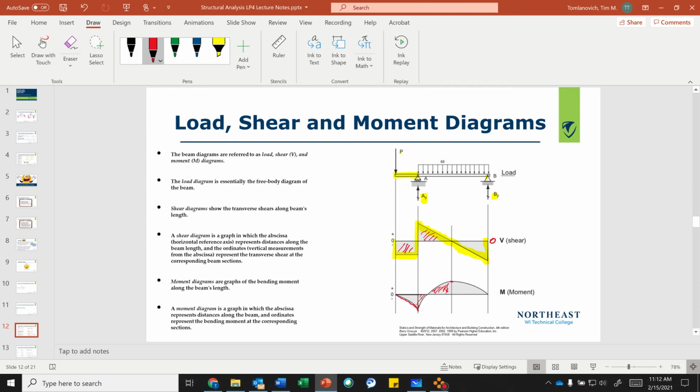So right here, as you see, 0 shear equals maximum moment. And then here I have a negative shear because I'm below the 0 line, so my slope is going down. I'll explain this in more detail. Okay, so these are actually fairly easy.